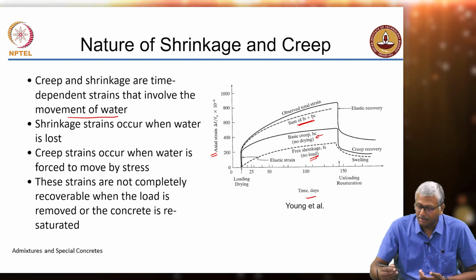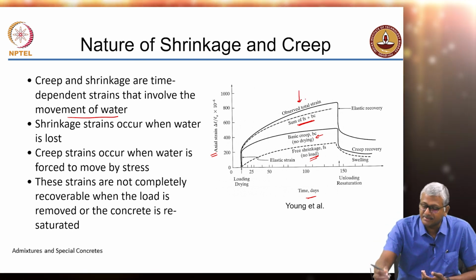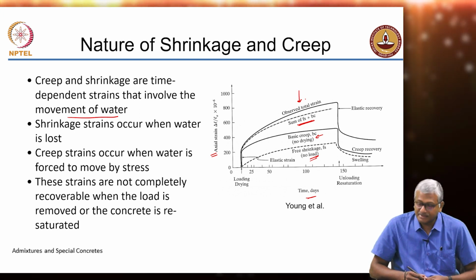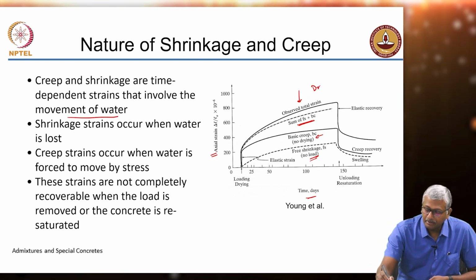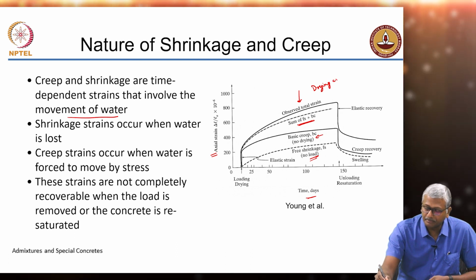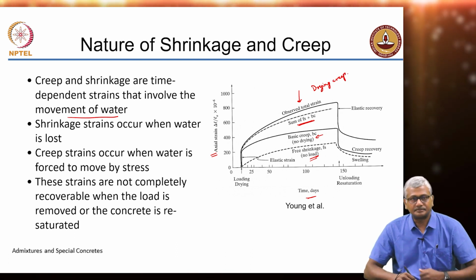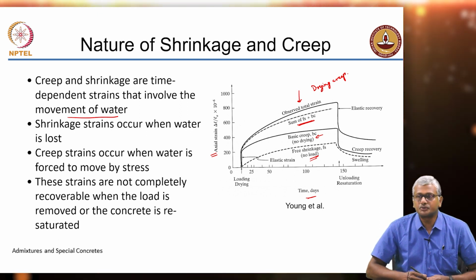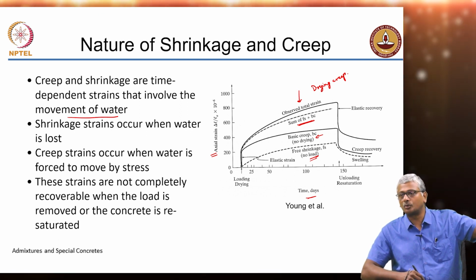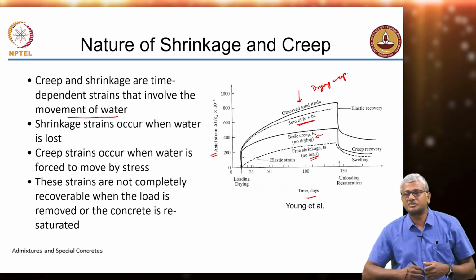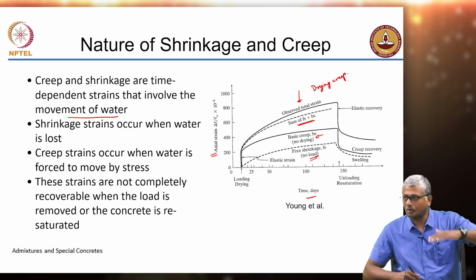But in reality, you get actually a total strain that is greater than the drying shrinkage and basic creep, and this is because of the presence of drying creep. In drying conditions, the creep becomes greater. Okay. So, in reality, let us say you take a metro structure, all the columns that are standing there, they are subjected to drying, they are subjected to a constant load.